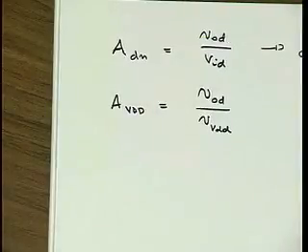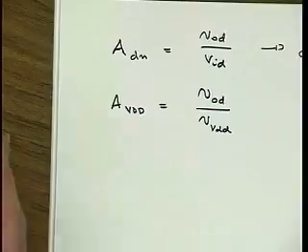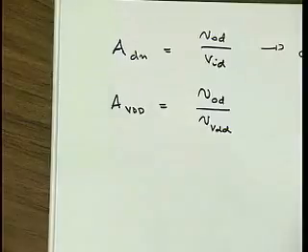And even if you measure it in the lab, that's what you do. You get your power supply, set it to 3 volts, and then you get a function generator and put a sine wave on top of it, right?